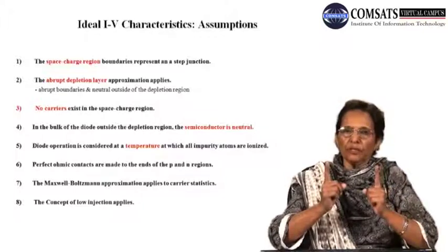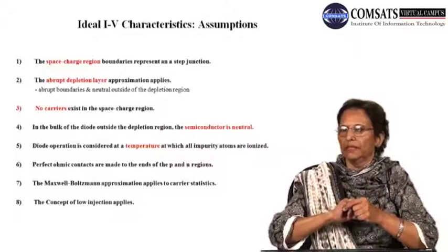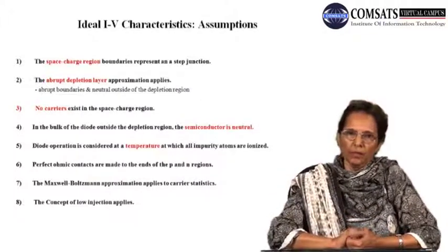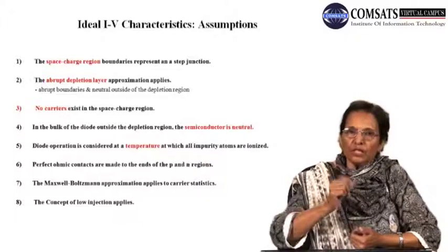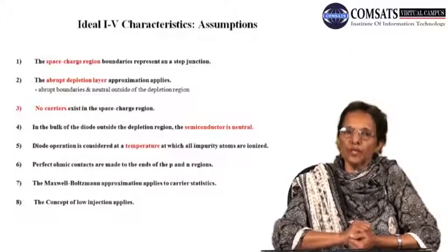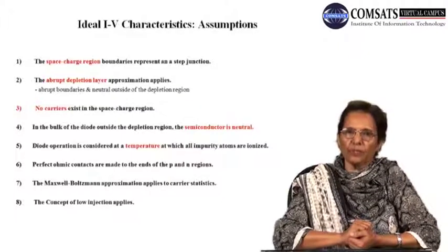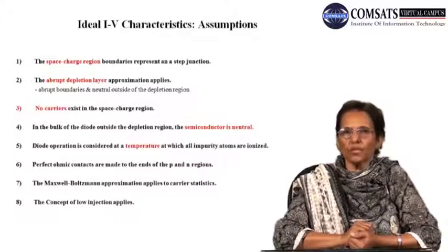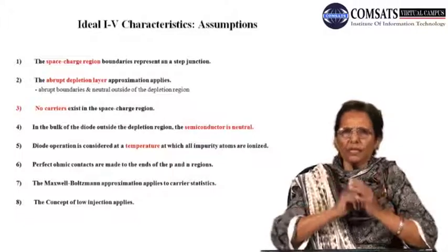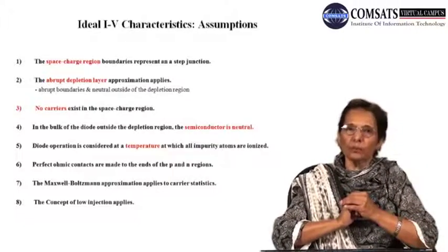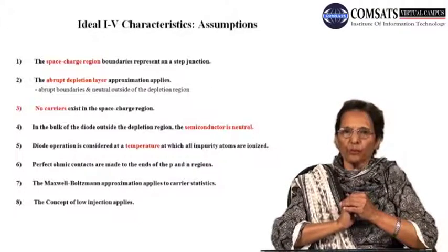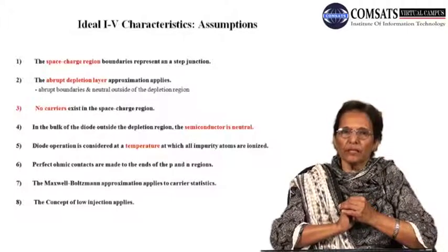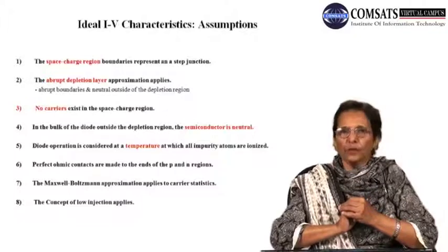You see, I just mentioned that there is a P region on the left side of the PN junction and an N region on the right side of the diode. The number of free electrons, the free mobile charge carriers in the N-type semiconductor material, is almost equal to the concentration of the ionized donor atoms. What does this mean? Each free electron has been obtained by ionizing an atom of the 5th group of the periodic table that we added into the intrinsic semiconductor material in order to make it N-type or extrinsic.